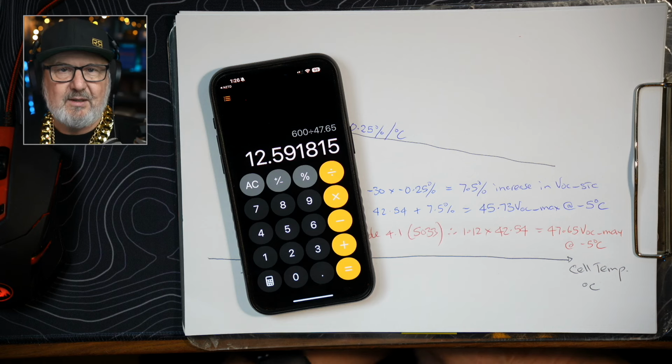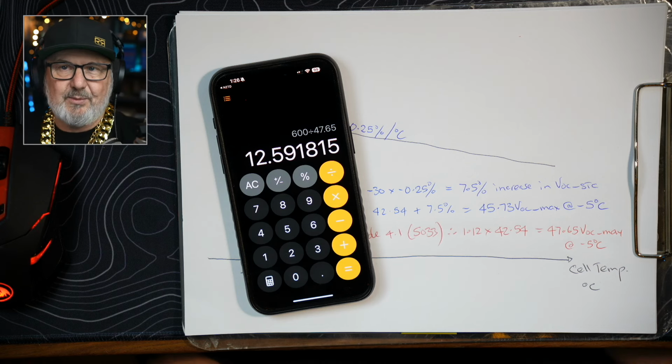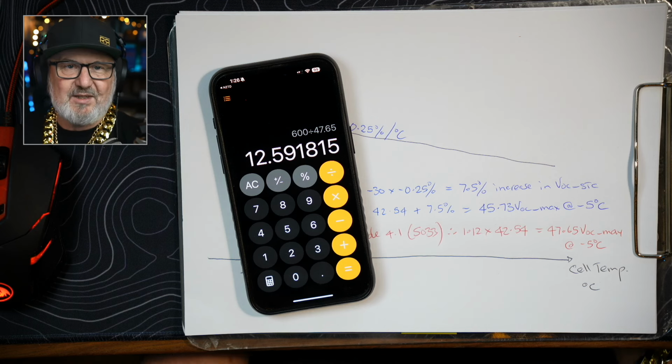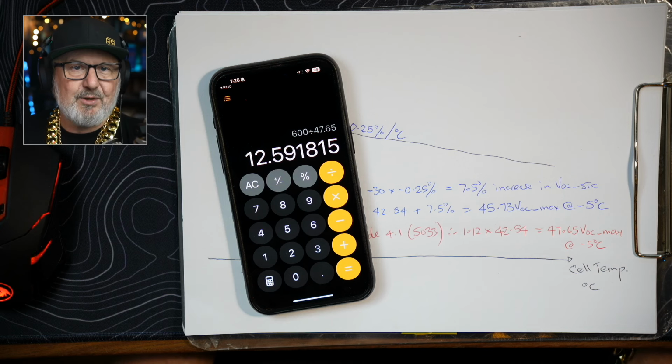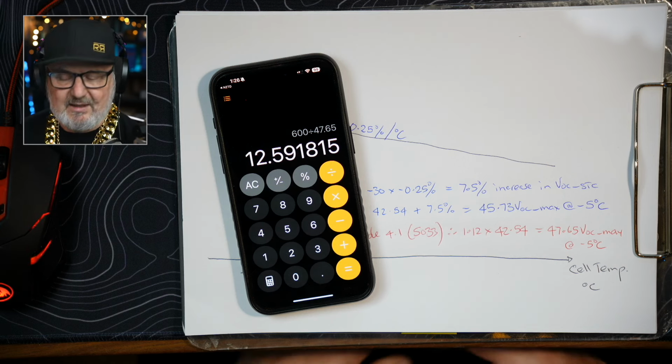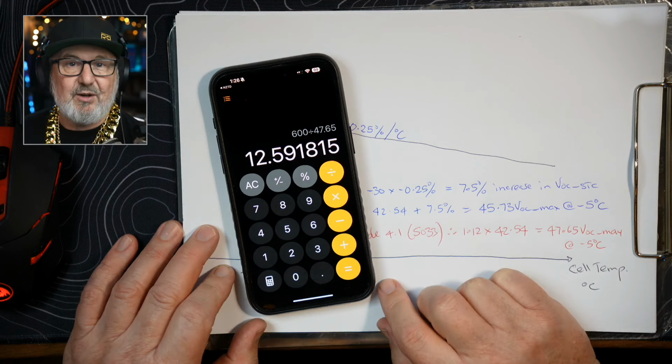Fun fact, I learnt this from an engineer friend of mine recently who designs inverters: the reason for 600 volts being so common, even when you're allowed to go beyond it, is that it makes inverters much more expensive because of the creepage, clearance and pollution requirements for going over 600 volts on a circuit board. So basically the PCB gets much more expensive to make over 600 volts. Clearances have to be enlarged. So yeah, it's about cost as well.